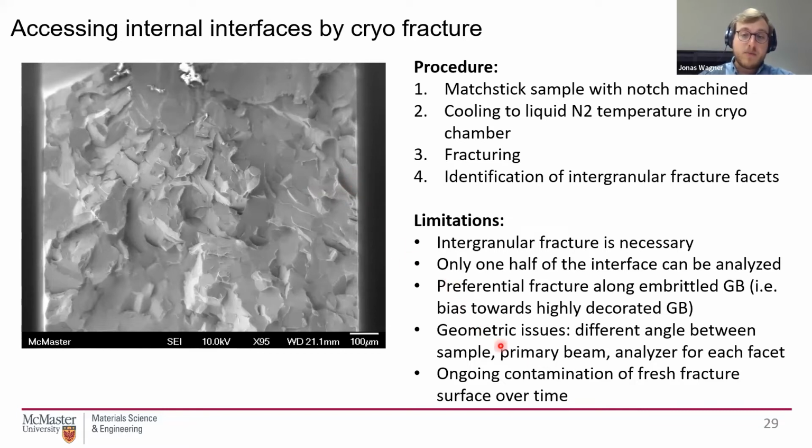Another thing to keep in mind is that the time you have to analyze such a fracture surface is very limited. Even though it's an ultra high vacuum, you see some contamination over time, some carbon depositing on the layer. So usually you should get this done within an hour before the carbon concentration becomes too dominant.